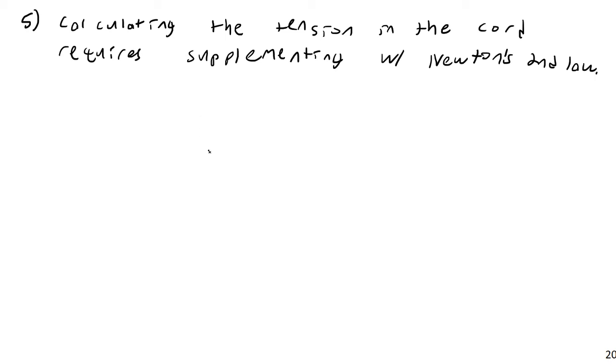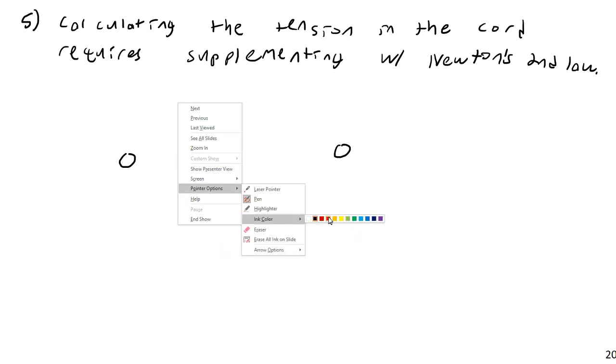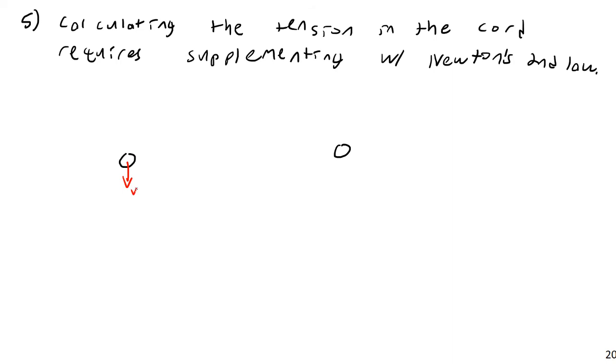So I'm going to do the same thing I did in the previous chapter, and draw a free body diagram and a kinetic diagram, or an inertial forces diagram. So the free body diagram would have weight pulling down, and the tension P pulling upward. And then this would be equivalent to the m a tangential and m a centripetal, or m a normal.